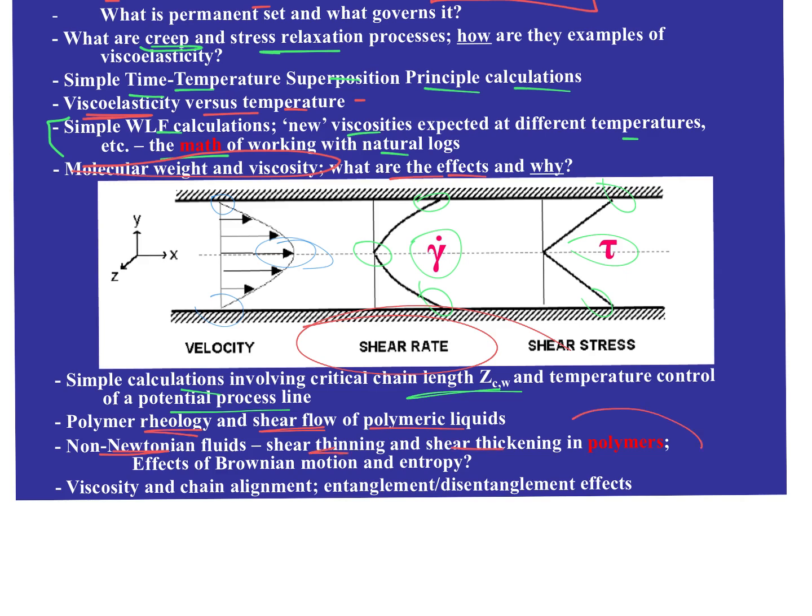And this has to do with, again, the polymer structure that's going on inside these systems, and issues of molecular weight. You know, those should be obvious factors in this concept of shear thickening or shear thinning. Bonding, secondary bonding, presence of polar groups, bulky side groups, all those things factor into flow here as well. All right, so what you've learned for solids still applies to liquids in this context. And then Brownian motion and entropy. All right, those haven't gone away either.